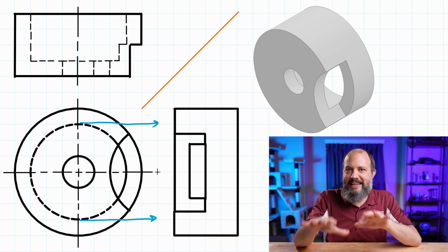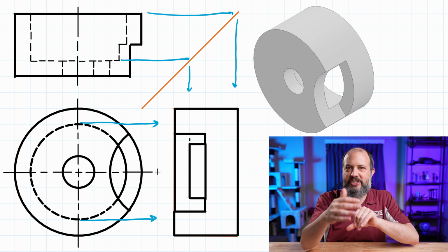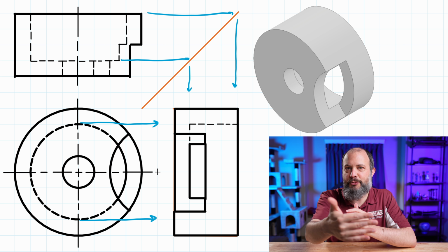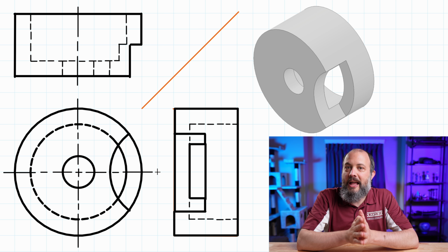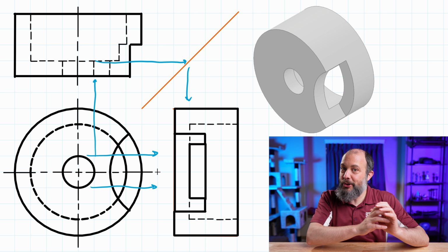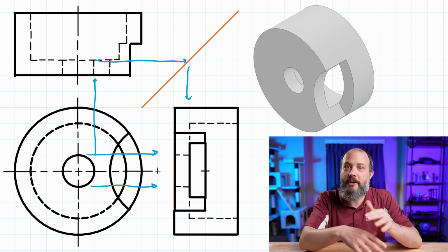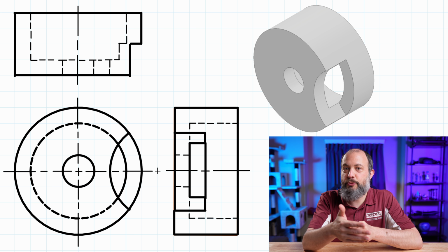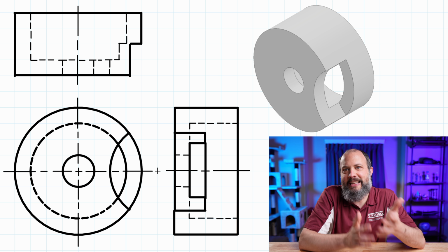There are, of course, some hidden lines. Using the larger circular cutout, you'll see hidden lines along the top and bottom of that circle, as well as at the depth, the furthest in that it's pushed. And then for the very smallest hole, you'll also see hidden dashed lines to represent the top and bottom of that hole. No vertical hidden line for this one though, because it coincides with a visible line that's already drawn, and visible lines have priority over hidden lines.